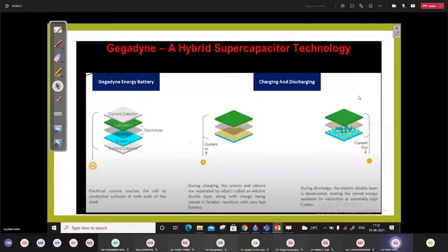So this way, once you find this, you can have the value of R, or rather the integer, positive value of R. You have to decide how many capacitors can be connected in parallel. So that way you can find out the sizing of the capacitor bank also. Of course, for that you need to know for how much duration you would like to provide this power to the load.